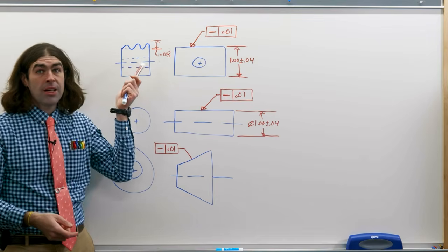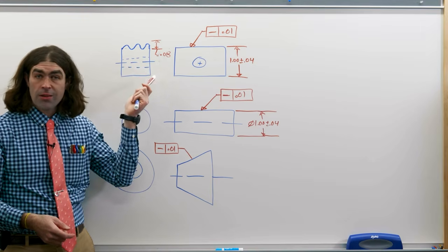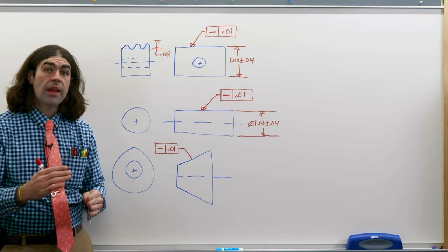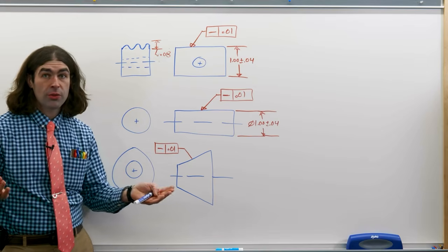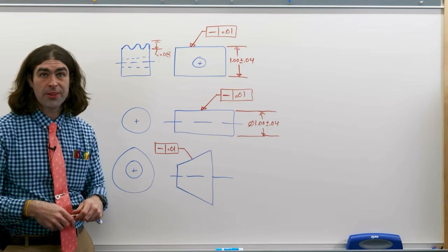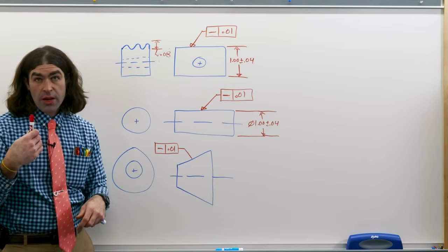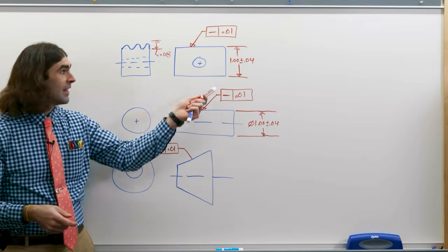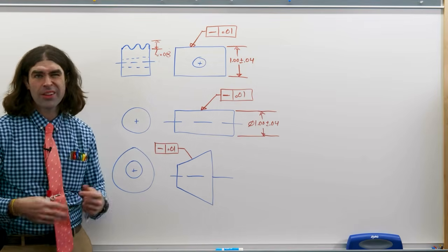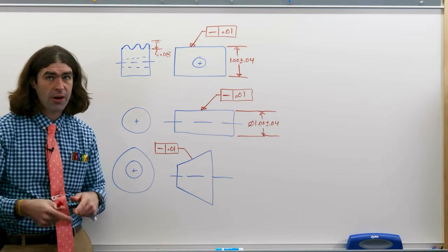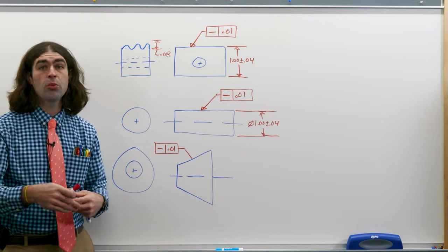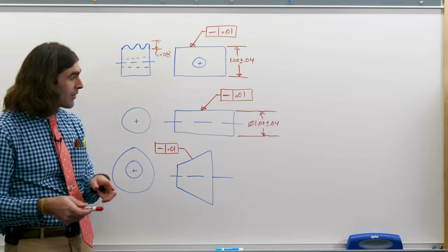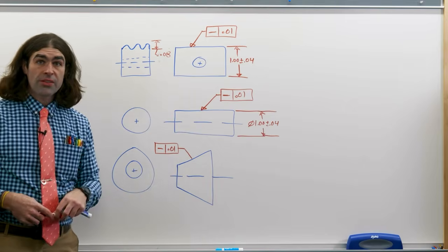Now, there are applications where you could get away with this corrugated roof thing. If you needed it to be straight in both directions, you would just use a flatness tolerance, which we'll talk about in a little bit. So straightness controls the straightness in one direction only, and it's usually indicated on a drawing like so. On a 3D model, it's got to be shown with an arrow or something. It's got to be more clear. In an orthographic projection, it's pretty straightforward. Next up, it can apply to a cylindrical feature.